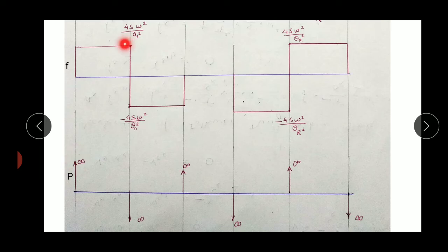Similarly, at the middle of the outstroke, you can observe there is a certain amount of constant acceleration, and suddenly within no time we are getting a constant amount of deceleration. So from positive acceleration to negative acceleration or retardation, suddenly the acceleration is changing within no time, as it is a vertical line and the slope of a vertical line is infinity, and the slope of the acceleration graph is jerk.